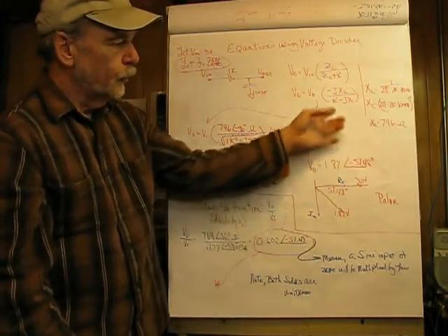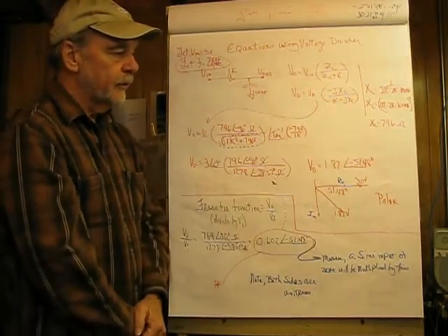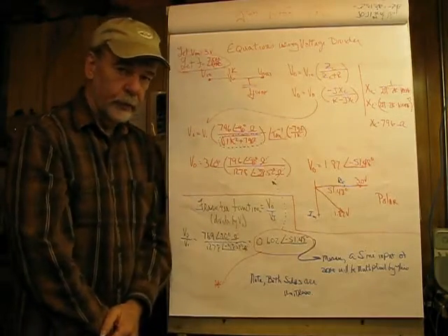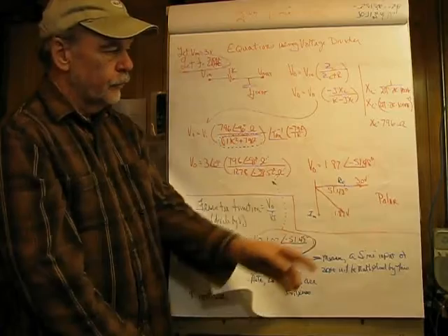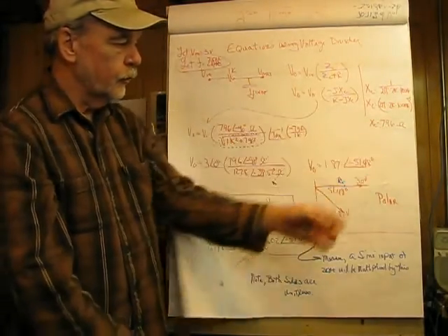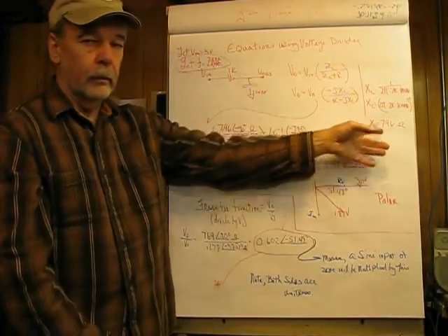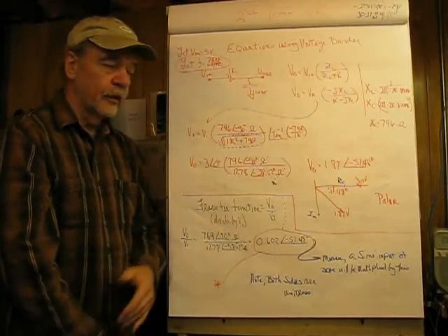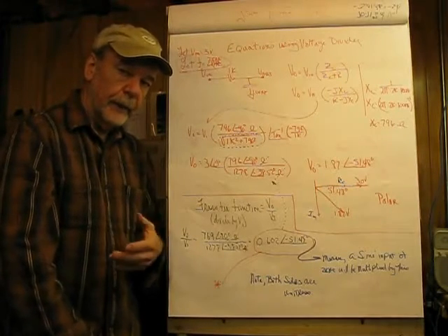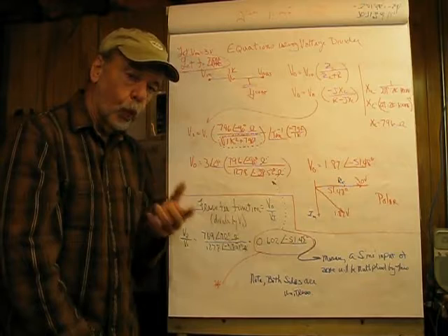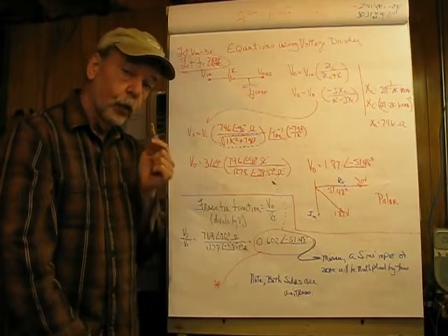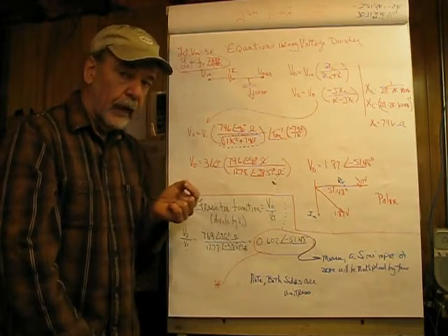Then to do this, we'll have to find out what the capacitive reactance is at 2 kilohertz. And that turns out to be 796 ohms. Now notice that there's no angle with this, and the reason is because I'm designating this a capacitive reactance. Those words mean that the angle is going to be 90 degrees.